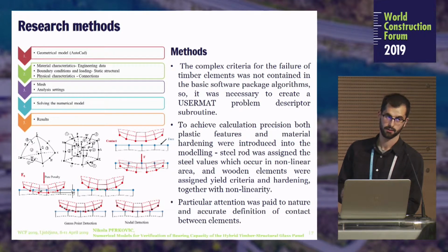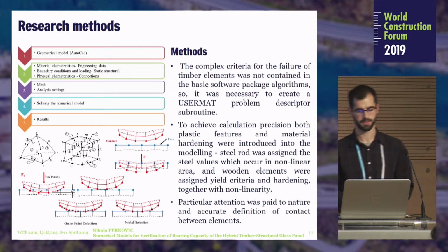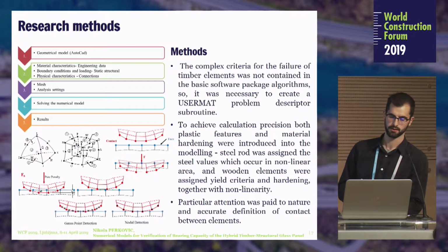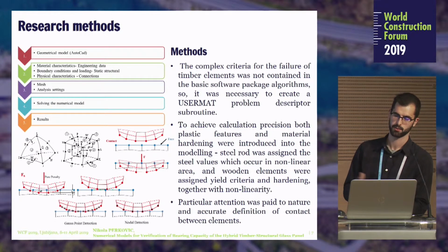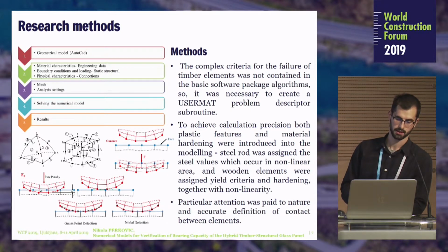After that we needed to find a proper mesh, not too big and not too small elements, because if you put very small elements the procedure will take a lot of time, and if you choose big elements then it's not really correct. That was one of the main problems, and afterwards we concluded that the results were actually good.